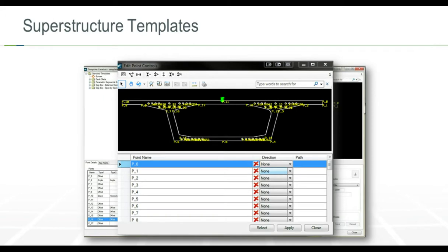On superstructure, this is a segmental portion in the center navigation spans. It all starts with the 2D line work. The great thing is that we can make a lot of parameters, and we can vary those parameters very easily. So in terms of varying segment depth and varying thicknesses, it's all very straightforward to do. Some of the things we've even tested a little bit is our own tendons inside, because the general segment geometry gets you 90% of the way there. But it's a lot of those little details and add-ins that can really take the model to the next level.